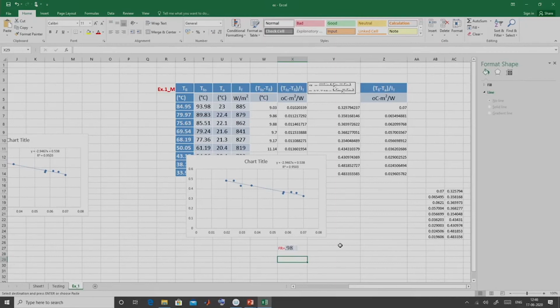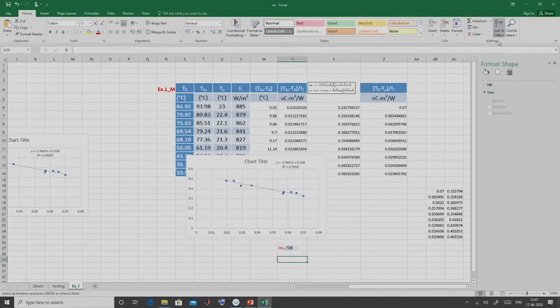There is no point in doing the characterization at different mass flow rates. But in the case of a solar air heater, experiments need to be performed at different mass flow rates, because the heat transfer coefficient on the air side is much lower than on the liquid side. So, we got a very close value of FR.